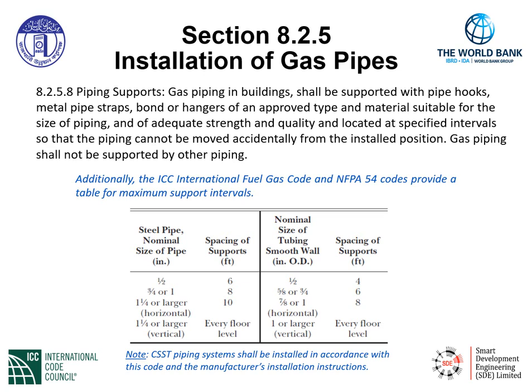So if we look at what is indicated as half-inch pipe, we know that to be 15 millimeter, and you can do the associated conversion for the spacing of supports, as well as looking at steel pipe again. 3/4 or 1 inch actually converts to 20 millimeter and 25 millimeter pipe, and 1.25 inch, 32 millimeter, and you can do the associated spacing of supports.